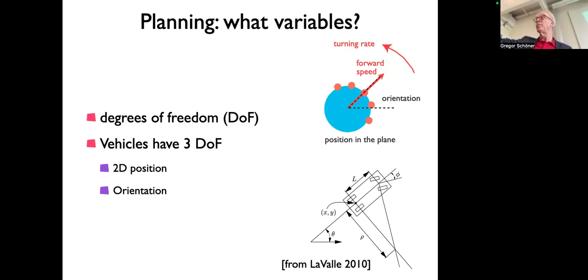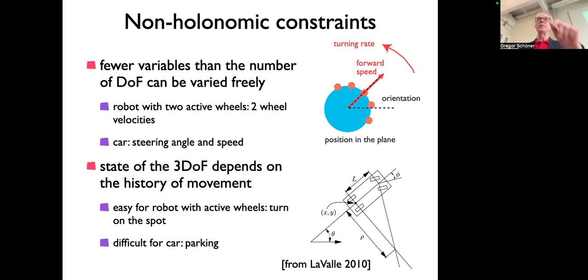So we can rotate it on a vertical axis, then on a horizontal axis, so 3. 3 rotational degrees of freedom. And 3 translational, because that would have 6, right? The rigid body. When you constrain the rigid body to a plane, it turns out that you have three left. The position is 2, and then there is the orientation, right? We think of the system as just like a disk, right? The orientation, so it's only 1. It's a bit odd. It's 3. So 2D position and 1 orientation.